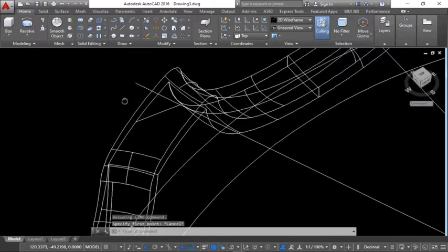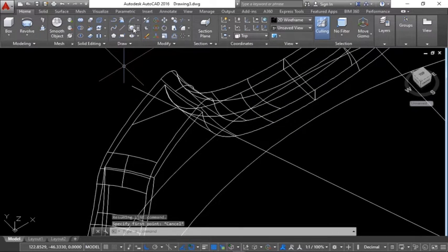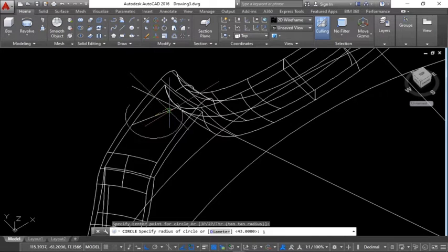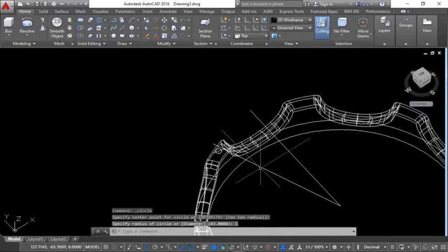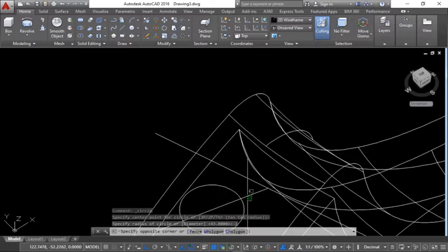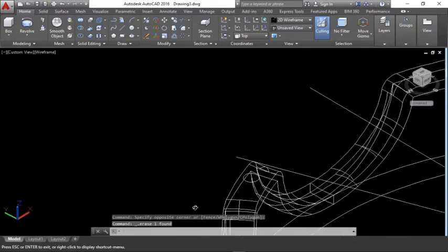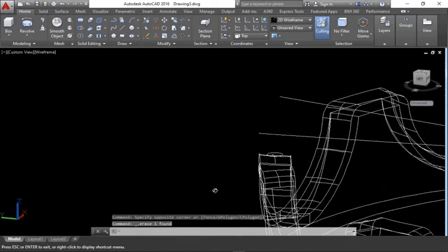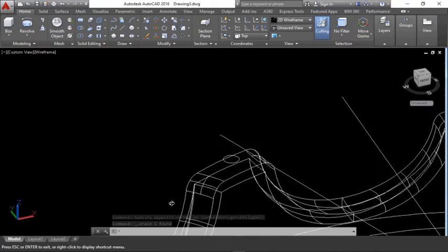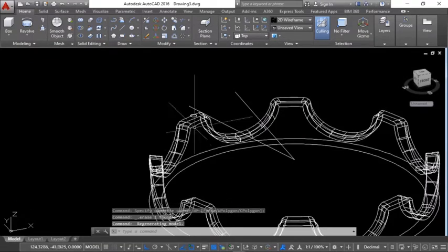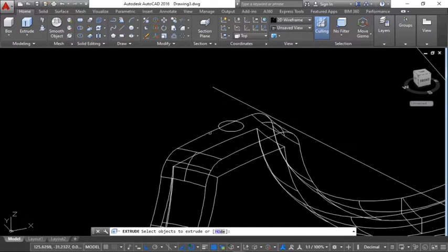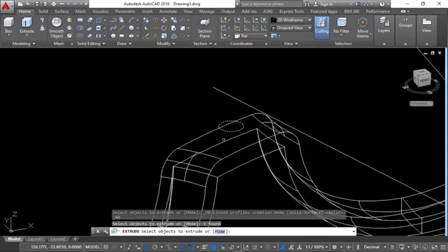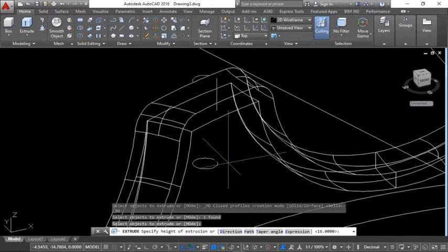So let's say a circle at this center here, with radius 1. All right, it's right, but I think it's diagonal, so you can delete that. Let's see where the position is. It's at the center, right? So all that you're going to do is select your extrude command, then select this line and this circle, sorry, you press pull downward.